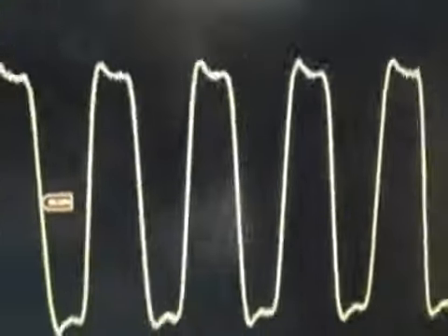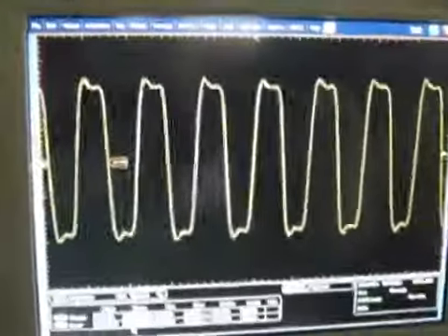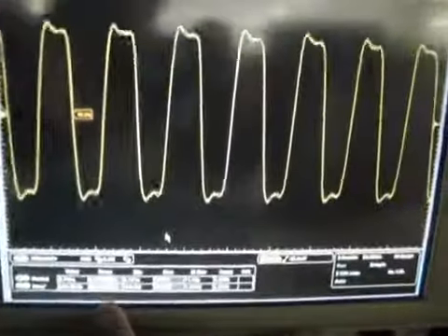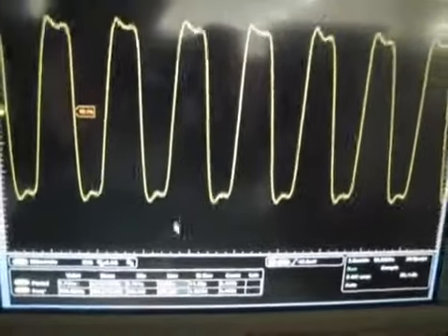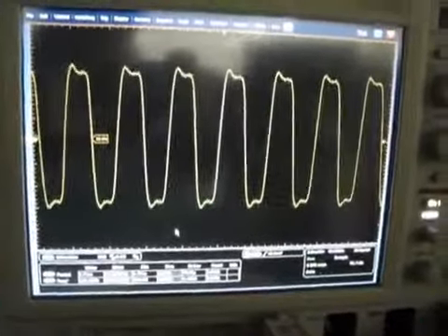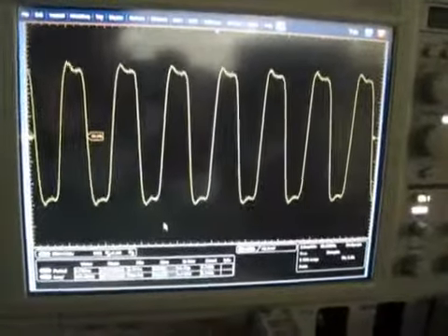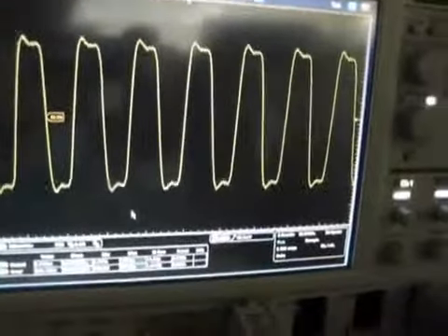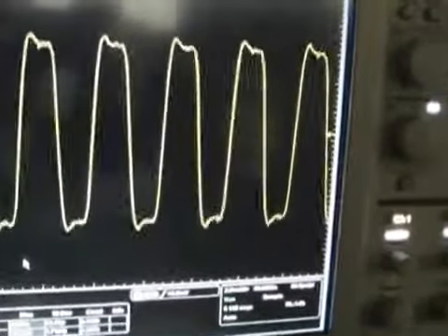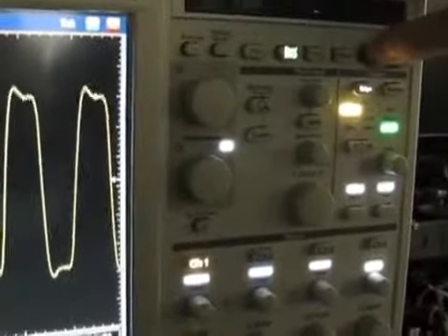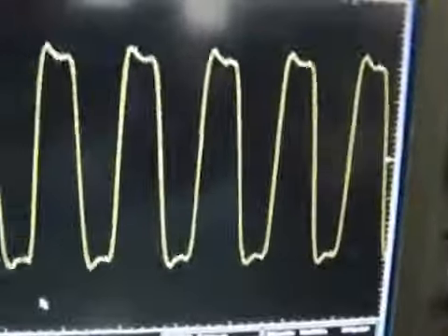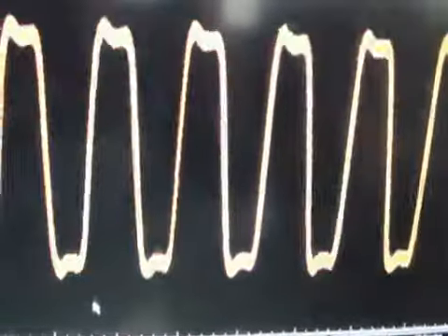Okay, if we go back to the scope screen, let's zoom in on this area. We will see the clock frequency is 364 megahertz. If we use the normal trigger and the normal scope mode, this is the signal we captured. Right now I'm going to turn on the Tektronix DPX technology, which means the waveform capture rate will be increased a lot, so it will capture a lot of waveforms in a really short time. So if we turn this on, okay, we will see